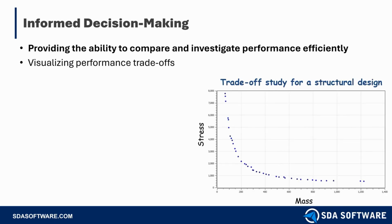So if we look at an example, a trade-off study for maybe a structural design like the one on the bottom right, we can see that in the vertical, we have stress, horizontal, we have mass, and these data points really showcase quite a clear relationship: when you reduce the mass of your structure, then basically you're shifting left, then your structure is experiencing more stress.